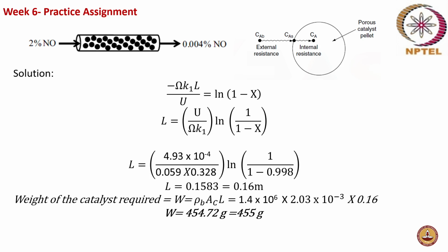And we found out that the reaction involving conversion of nitric oxide to nitrogen is limited by both external mass transfer resistance and internal mass transfer resistance, as your Weisz-Prater parameter was much greater than 1, indicating that there is an internal mass transfer resistance offered, and similarly your Mears parameter was greater than 0.15, indicating that there is an external mass transfer resistance being offered for the reaction.